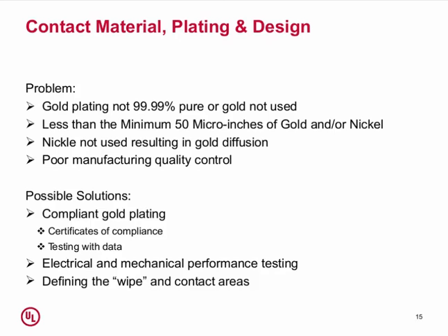Have the manufacturers or the people that are doing the plating actually run tests, provide you with the data as proof that they know what they're doing and providing a consistent product that meets the necessary requirements. You can do electrical and mechanical performance testing. If you don't have the proper gold plating and you do an insertion type test, you can do it to destruction, but if you're doing 500 insertions, 1,000 insertions, without the gold plating, you're likely to see failures. With gold plating, you probably won't have any problems.